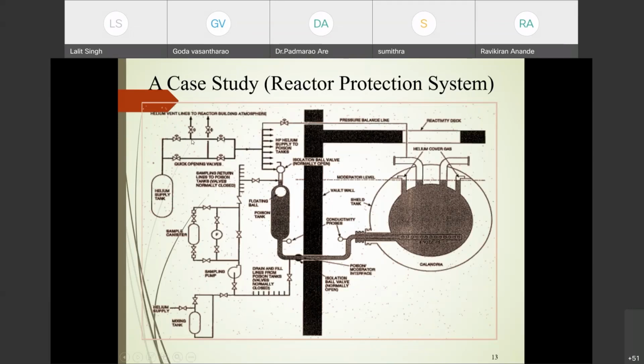So what should happen? I should be able to devise a mechanism so that I can release the pressure in that line between these two valves. For that, to tackle this scenario, I have put one additional valve that is known as the vent valve, to vent the pressure in between these two valves in both the parallel lines. And hence, these vent valves should be open all the time during normal operating condition of the reactor.